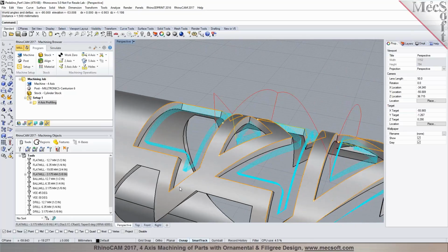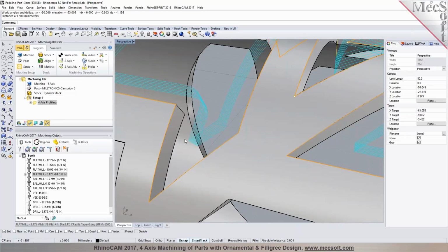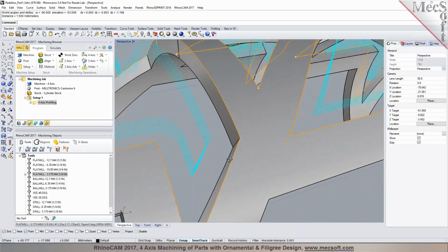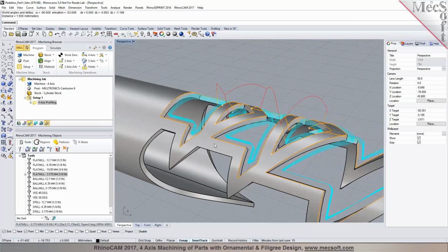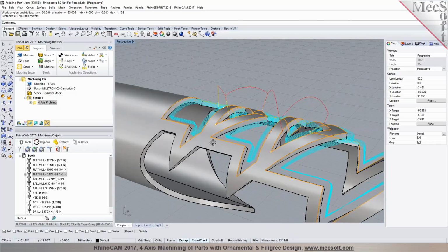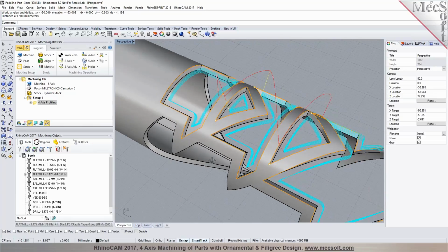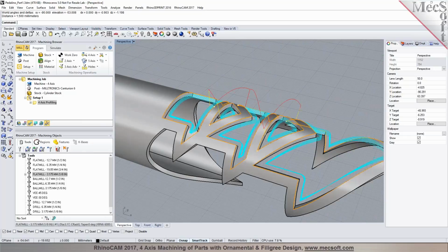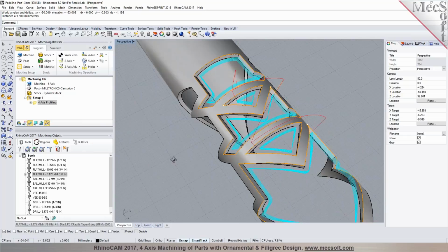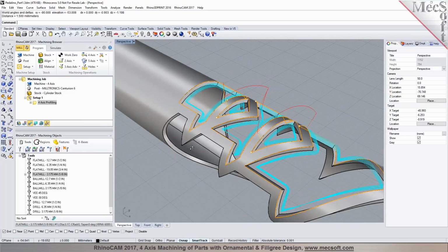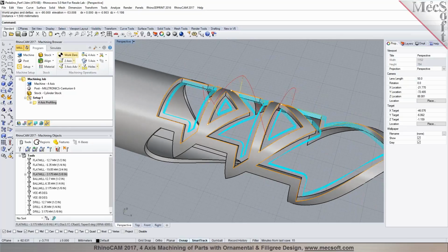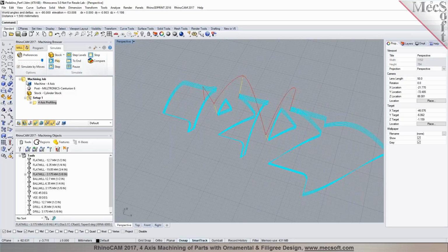And if the cutter is too big to fit into it, it's not going to gouge the part. Well, we're going to have a radius in each corner anyway, it's just not on the drawing that way. So what I programmed here was a profile cut, as you noticed. It just follows the contour around it.